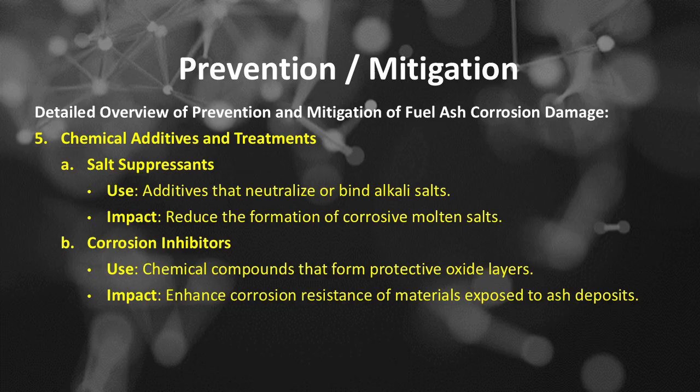Impact, reduce the formation of corrosive molten salts. Number B, corrosion inhibitors. Use chemical compounds that form protective oxide layers. Impact, enhance corrosion resistance of materials exposed to ash deposits.